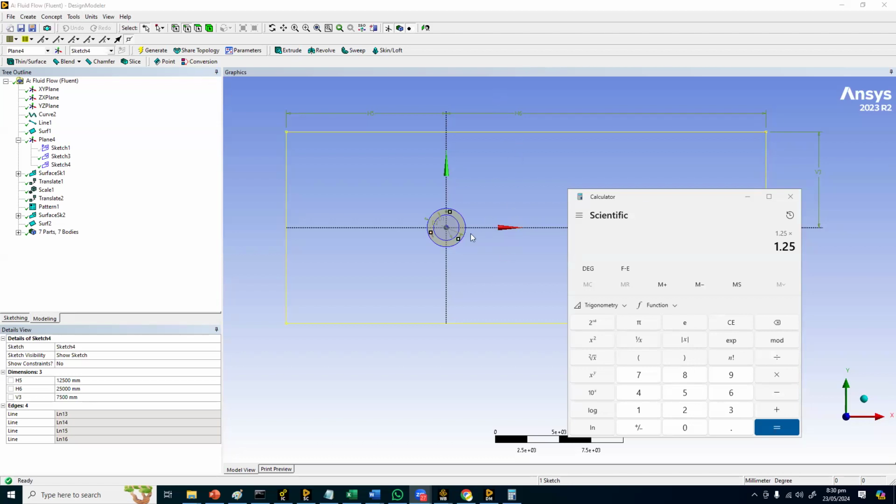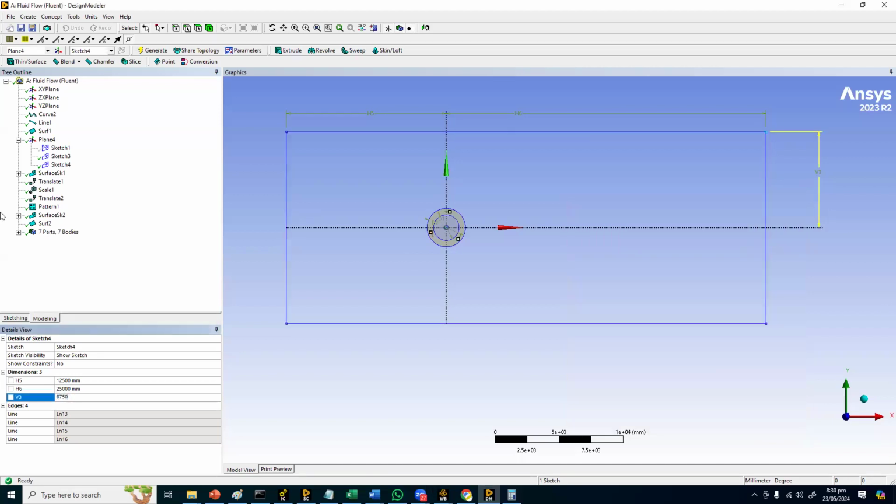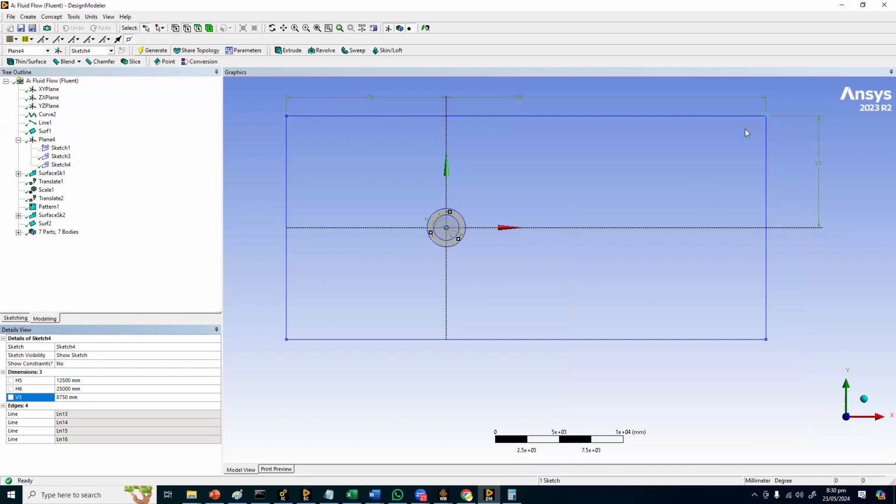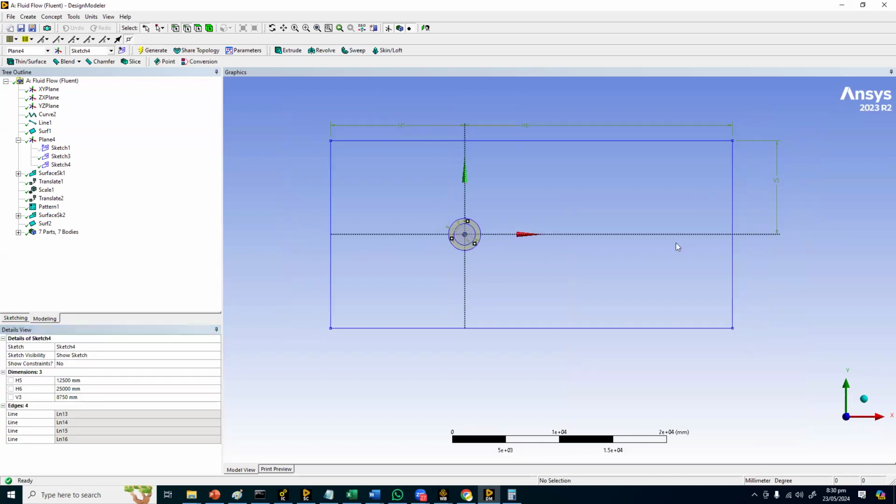Okay, so what I'm saying here is that right now we put 3 diameters from the x-axis to the top boundary and the bottom boundary. So we have put 3D here. So let's make it 3.5D. Okay. So 3.5 into 2.5 and then multiply with 1,000. This will be 8,750. So 8,750 and click on generate. So now it's 7D, 5D and 10D.